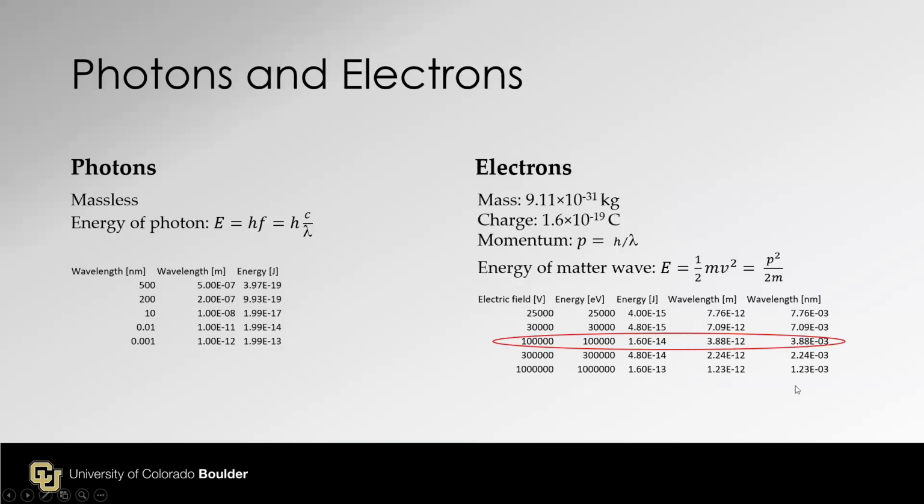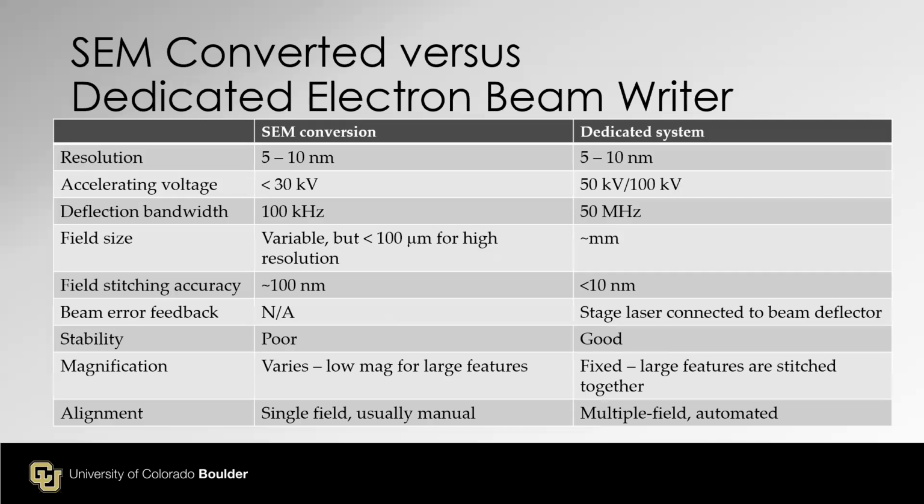Okay. So the beam size, well, 100 kV, higher, important. So 30 kV, that's typical SEM energy. Not bad, it's still small relative to photons, the mercury lamp in particular, but higher is better in terms of resolution. But resolution is not the only important thing in EBL.